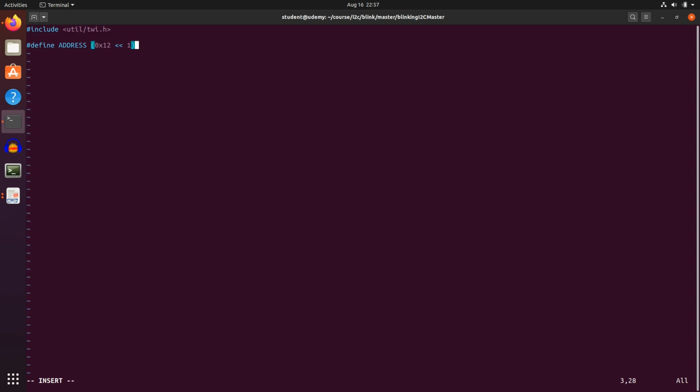Let me define this direction bit immediately. I2C_WRITE, which is 0, and we define I2C_READ, which is 1. So if I want to write to slaves, I use I2C_WRITE, and if I want to read from slaves, I use I2C_READ.